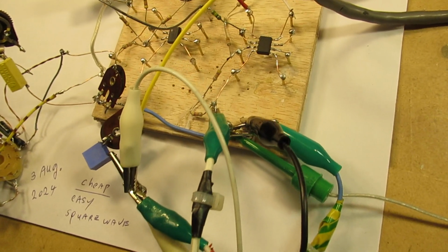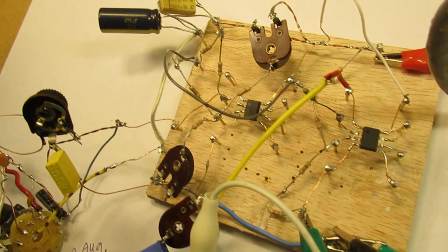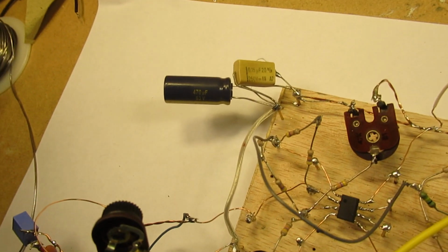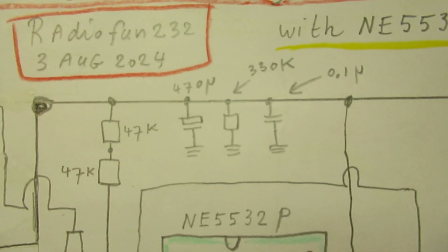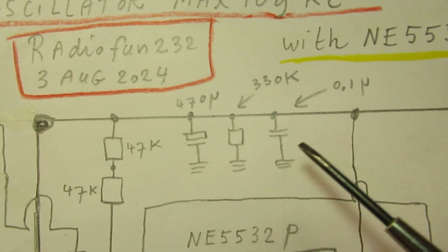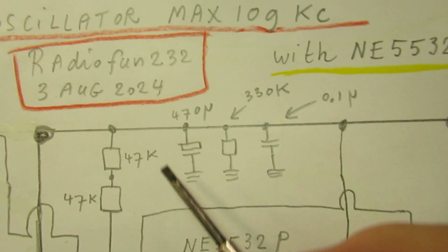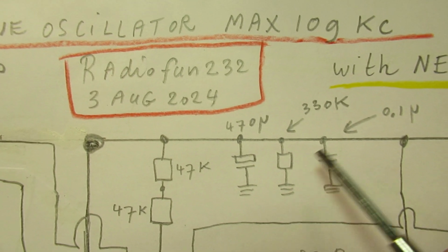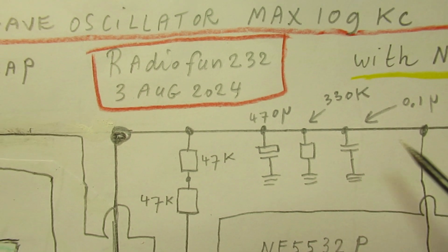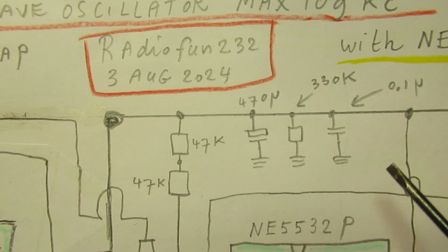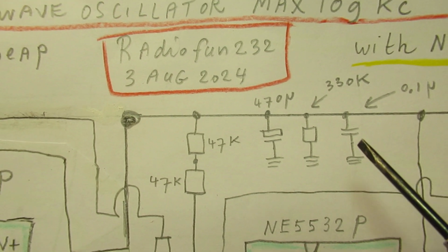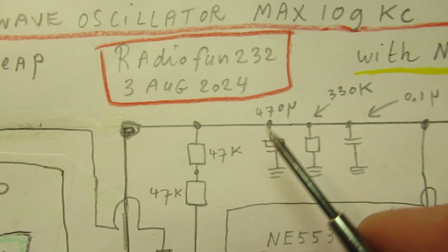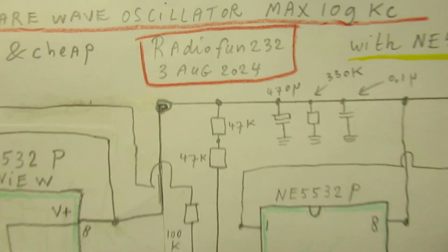Pen over somewhat. And this is perhaps interesting to tell here. The decoupling unit is here, 470 microfarad, etc. I have used this because perhaps when you want to make it, your power supply is not pure enough. That's the reason why this kind of filter is used.